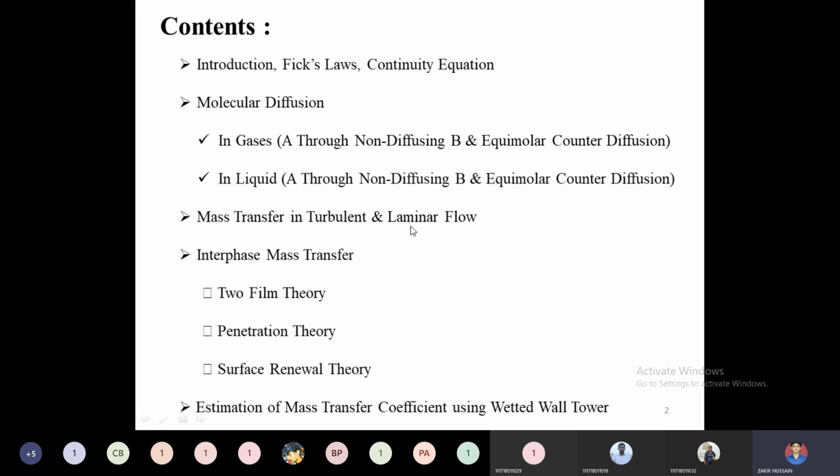Similarly here also, for the conduction case, you can refer to this as a conduction mass transfer case. For the conduction mass transfer case, the governing law is Fick's first law of diffusion. Whereas for convective mass transfer, we need to have a mass transfer coefficient. When more than one phase is present, mass transfer coefficients are a very convenient criterion to express our mass transfer process.